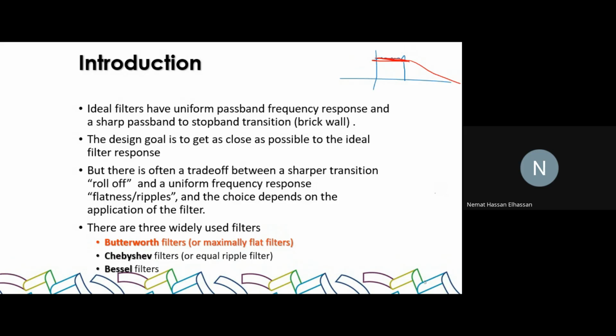And then you select what frequency response you want. How do you want the filter to behave? And then based on that, you select the value of the resistances and capacitors based on your cutoff frequency, okay? So usually it's the opposite. It's reverse. You don't start with a circuit and then derive the function. You start with the required function, and then you derive the value of the components that you need to create that, okay?